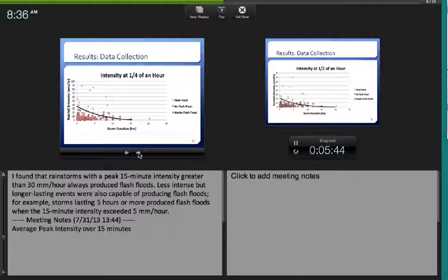This threshold curve starts around 30, 35 millimeters an hour, which, to put in perspective, heavy rain is generally 15 to 20 millimeters an hour. So that's pretty intense rain that needs to happen. Likewise, if the storm is reaching about 15, 20 hours, all it needs to do is just rain for a long time at like 2 to 5 millimeters an hour.